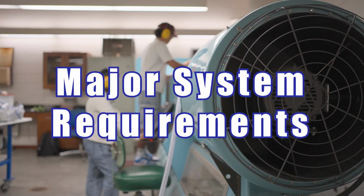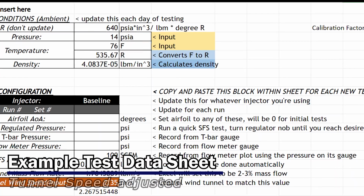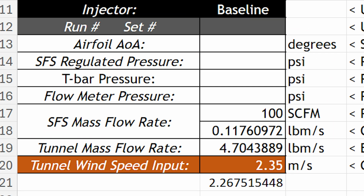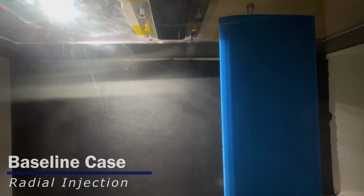We were required to recreate the Honeywell injection problem. For our injector design, the mass flow rate of the SFS was required to never exceed 2 to 3% the flow rate of the wind tunnel itself to more accurately simulate the conditions in the compressor. We were also required to reduce the adverse pressure gradient caused by radial injection by at least 40%.